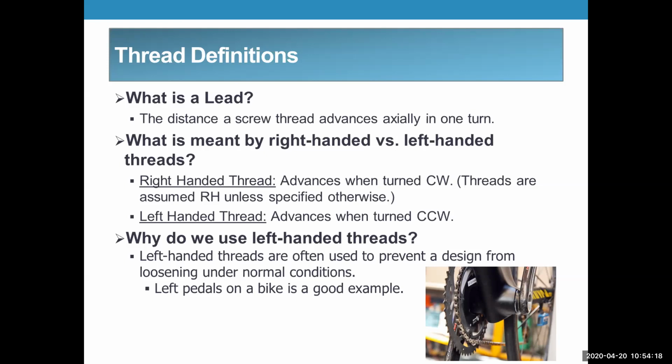It'd probably be okay, but might be on the verge of hitting the yield point. And if your torque wrench isn't accurate, you might over torque it, or if you don't use the right technique, you might over torque it or under torque it. But a 3/8 diameter lug can't handle the amount of torque that a 5/8 could, for obvious reasons. You've got more area to spread the load across.